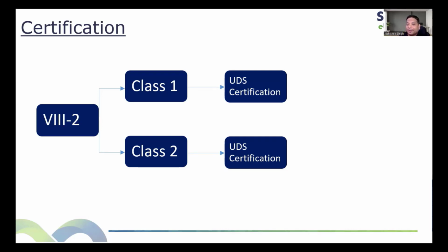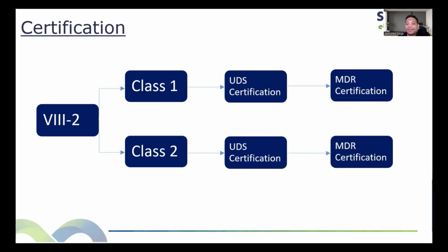Next document will be MDR. MDR will be prepared by the vendor or the manufacturer. What do you think, does MDR need to be certified all the time? MDR, which is the manufacturer design report, do you think it needs to be certified by a professional engineer? For MDR, if it is class 1, does it need to be certified all the time? The answer is no.